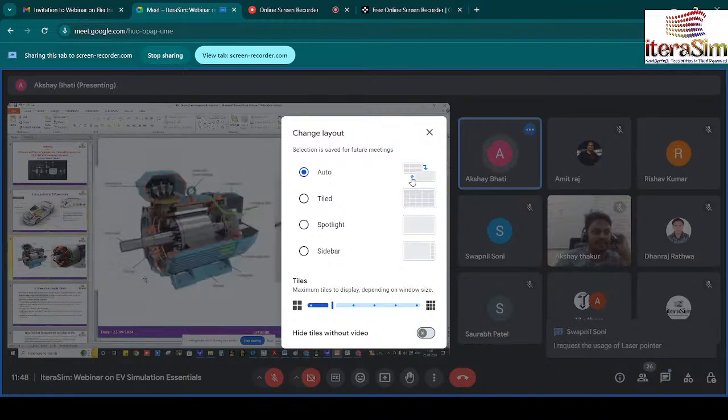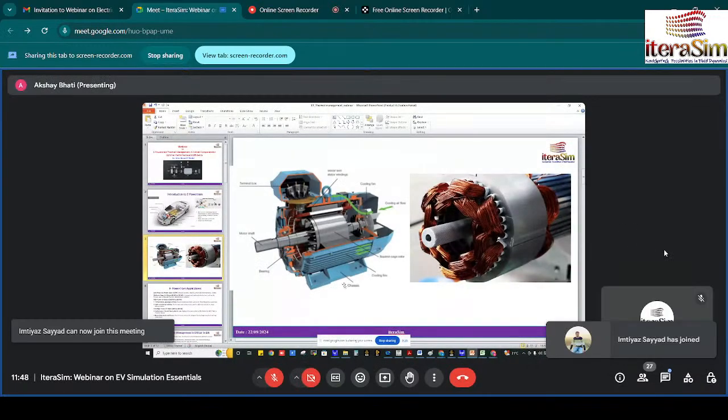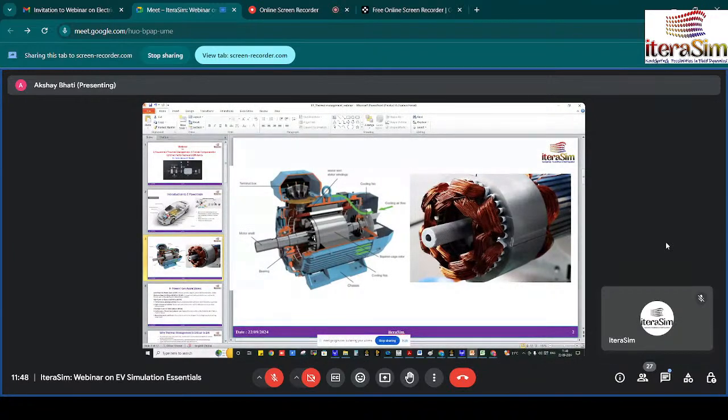And next is the architecture of the EV traction motor. This is a mid type of motor in which you see there is a shaft, and the rotor in which magnets are placed to generate the electromagnetic effect. After that, there is a stator in which the winding is there. On the left side you will see the copper winding, and the white material is insulating material. It prevents current leakage from the winding to the stator of the system. Here you see the open end of the winding, which is called end winding.